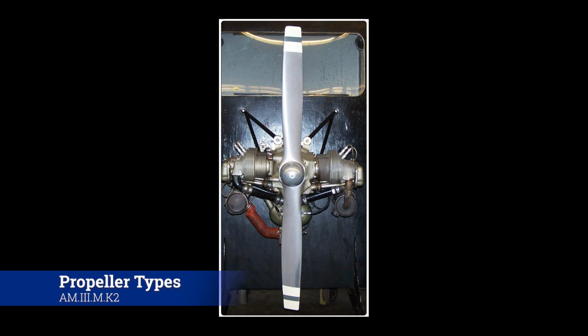And there's not that much to say about it. They're very, very simple. The thing you're going to be looking for whenever you're inspecting them is, what does the leading edge look like? Has it caught a rock or whatever? Do we need to blend that down? And are there any cracks or corrosion? That being said, I don't think I've ever seen corrosion on a prop that I can remember, at least. Maybe on certain ones you might get some oxidation here or there, but for the most part, I can't remember seeing corrosion anywhere.